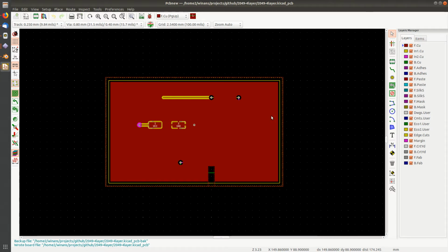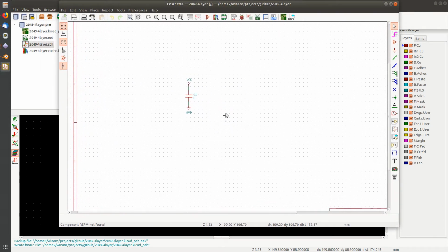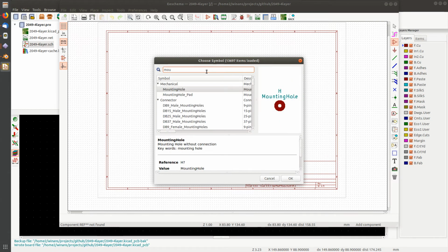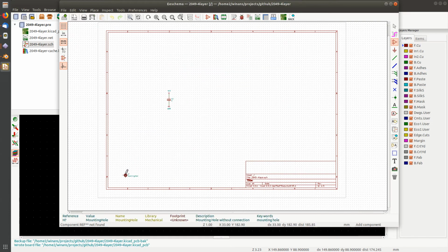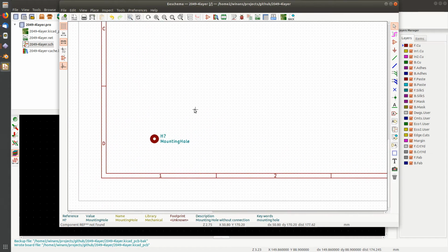But let's say for some reason you're not going to lock them, or better yet, you want a plated through hole. Okay? If they're going to be plated, there are actually schematic design elements. So let's go in here, and you've seen this if you look around, sometimes you find projects, schematics out there, where in the schematic itself you see mounting holes. All right? Now, this is why. They are real design elements. They need to go on the board.